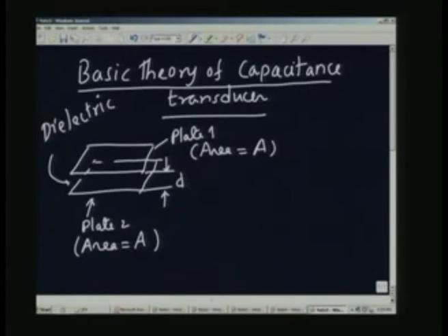In most applications of the pressure transducer, it may be simply air, or it may be some other fluid which may be there. The different materials which may be present here change the capacitance of the capacitor actually, because of the property of the particular dielectric medium which is going to be present there. Before we go into that, let me just write an expression for the capacitance.